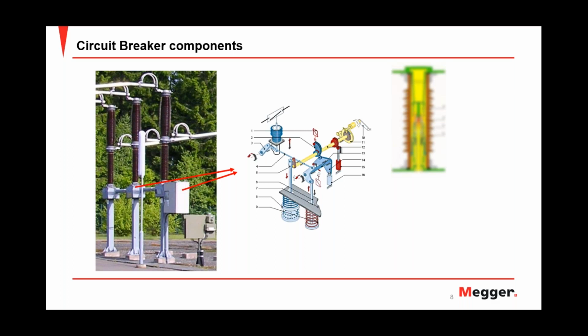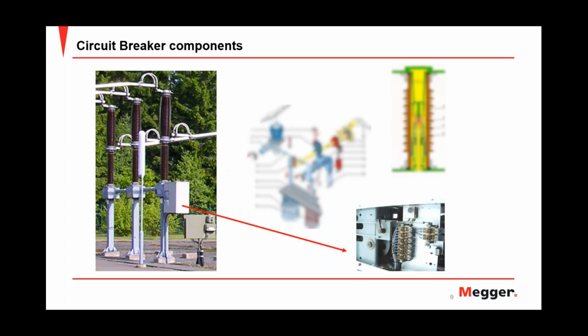Sometimes this part of the circuit breakers gets overlooked by some from a maintenance point of view. In the same enclosure, a number of auxiliary contacts are usually found, which are used for multiple functions internally by the circuit breaker as operation interlocks, position indicator for the bay control units, part of the substation interlocking schemes for protection functions.